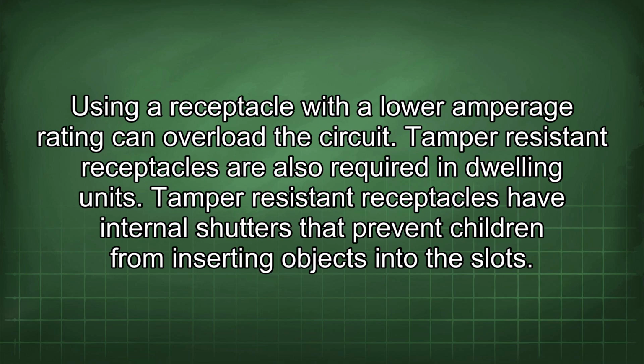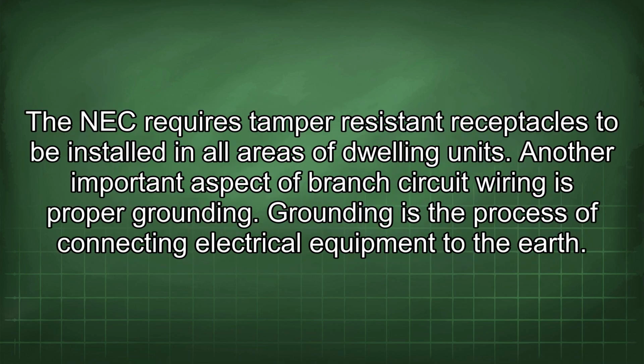Tamper-resistant receptacles are also required in dwelling units. Tamper-resistant receptacles have internal shutters that prevent children from inserting objects into the slots. The NEC requires tamper-resistant receptacles to be installed in all areas of dwelling units.